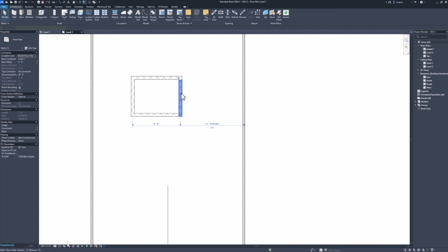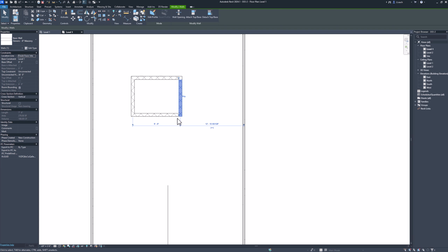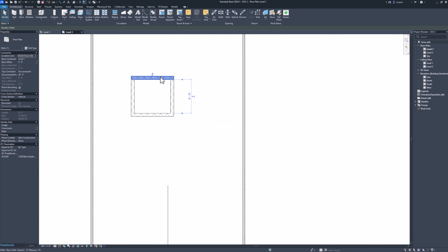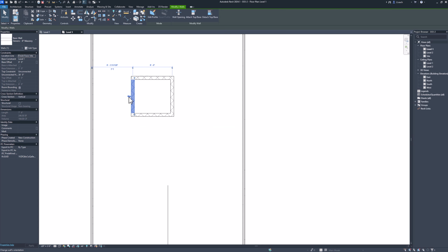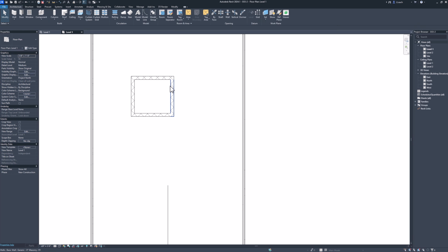And then I'm gonna select one of the vertical side walls, make sure that I'm measuring to the inside opening here. And this dimension is going to be 7'4". Just making sure our arrows are on the outside. So there's our elevator shaft, and we have it to the dimensions that's required.